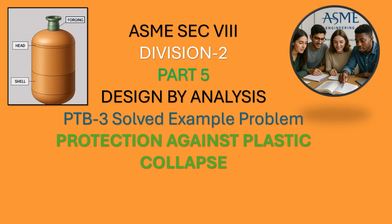To summarize the three methods: elastic stress analysis showed the stresses were within allowable limits. Limit load analysis confirmed the vessel could sustain 1.5 times the design pressure. Elastic plastic analysis confirmed stability up to 2.4 times the design pressure. All three methods demonstrate that the top head and shell region of the vessel is adequately protected against plastic collapse.